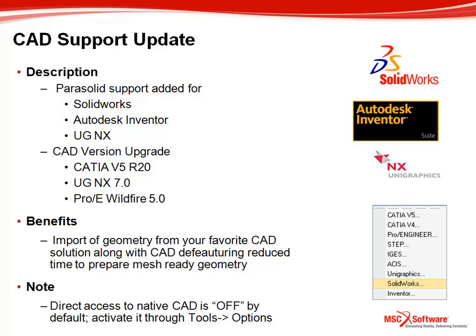And one note I have here is native CAD by default is off for this release. But users can quickly activate it through the Tools Options menu in SimXpert. On the right here, I have a quick dialog box that shows some of the geometry formats that are supported for Parasolid import with this release.